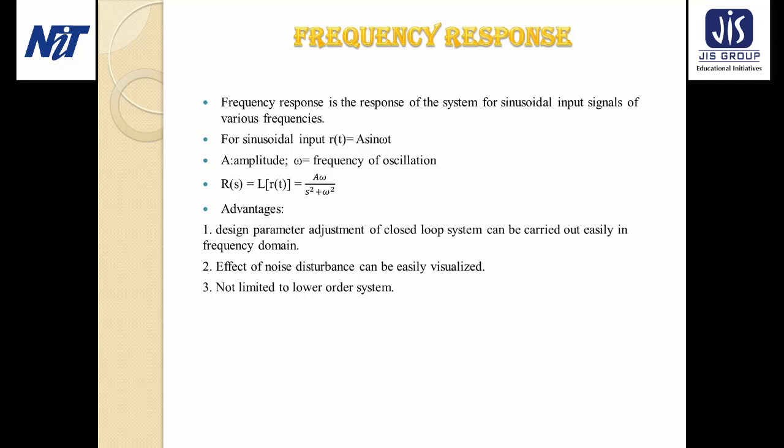And we know if the sinusoidal input is expressed as r(t) equal to A sin omega t, then if we consider the Laplace transform, it becomes A omega by s square plus omega square.